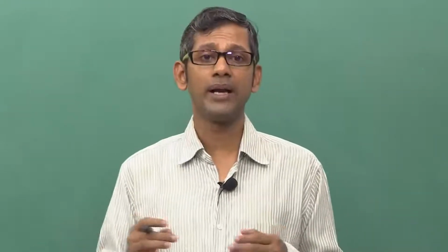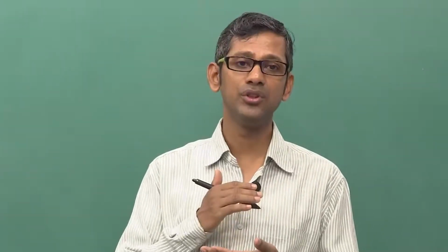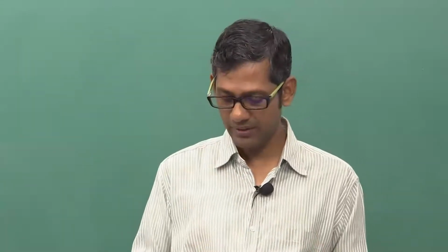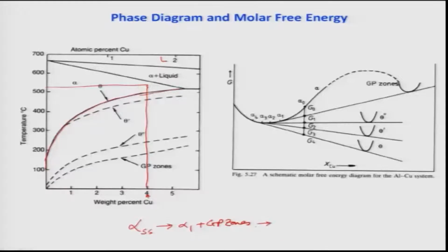So this is actually a copper atom layer, 2 or maybe 3 layers of copper atoms, sitting on the aluminum 001 planes, that is, the Z axis planes. Now if you heat it up or keep it a long time at 150 degrees Celsius, this will transform into alpha plus theta double prime. Okay, we will discuss this structure, theta double prime, later.